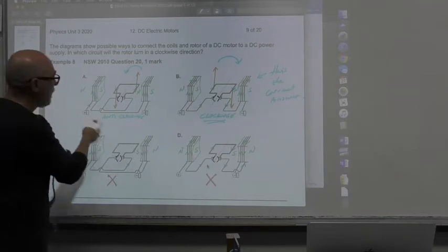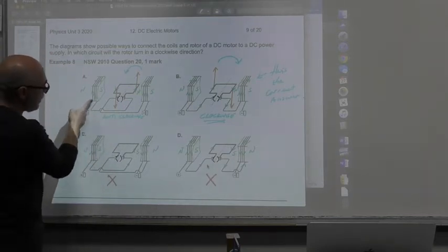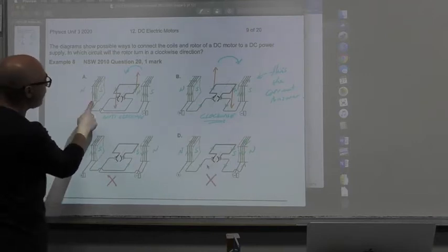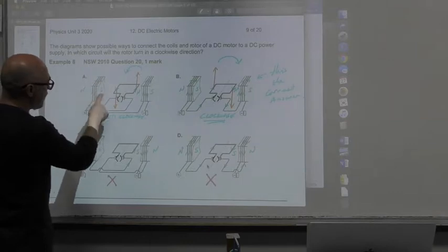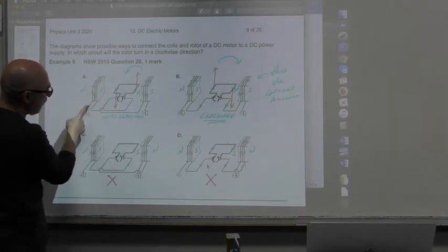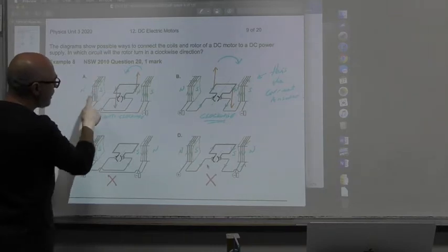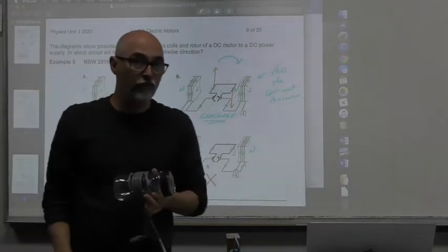You look at this wire as it goes in, connected to the positive terminal. It hits the front face of this block of metal and goes straight up, and then goes around and around. So you can follow that and put your arrows in along the wire, telling you which way the current is moving through the solenoid.